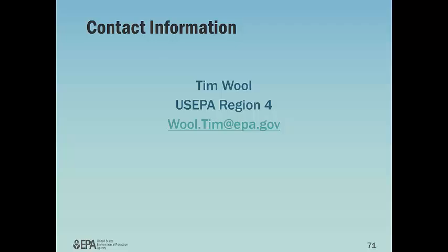So we're using watershed models linked to the receiving water body models. And we can determine the difference between anthropogenic and non-anthropogenic by looking at the land uses associated with it as well as the direct discharges. So we can separate out and know the difference where each component is coming from.